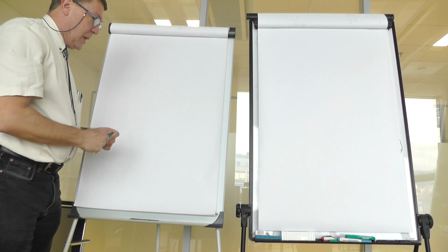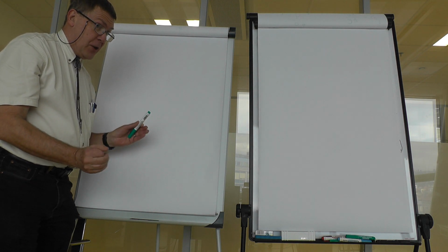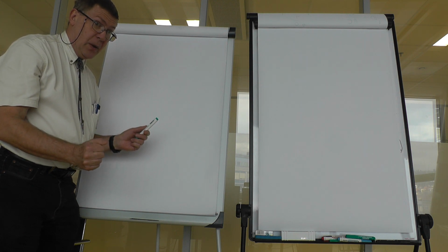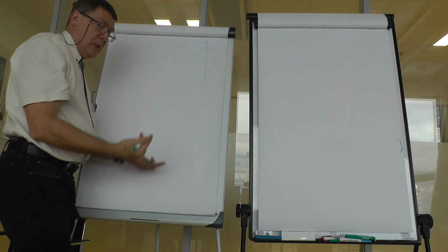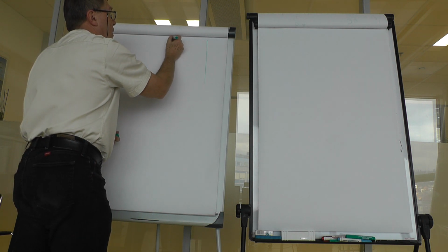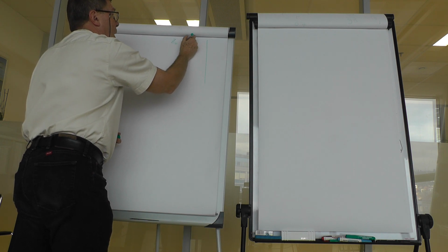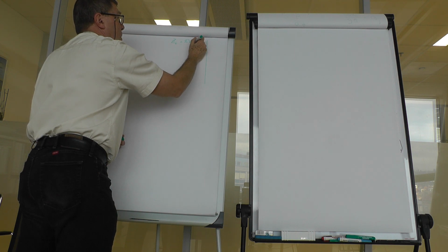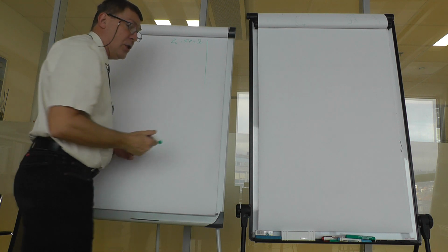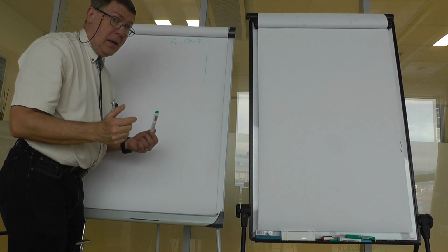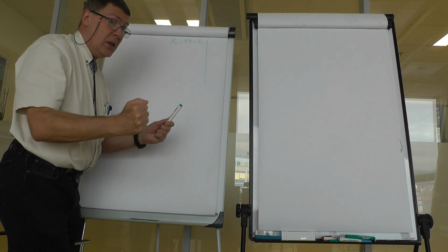So the first important point is the reflection. Let us describe the reflection in the case of a perpendicular incident wave. So we have a boundary between the air, for example, with characteristic impedance or wave impedance 120 pi ohms, and some material which is now designed to not reflect the wave.